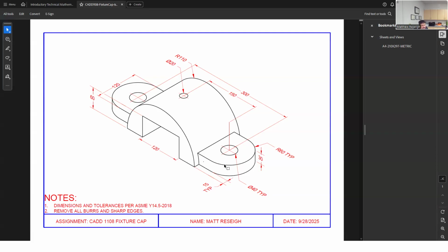And so 300 millimeter plus their radius, and this looks like it's a 60 and typical, meaning on both sides. So 300 plus 120, 420. Yeah, so 420 millimeters wide by whatever height this is. It's this radius, 110. So that's definitely my rectangle that fits in, 420 by 110.